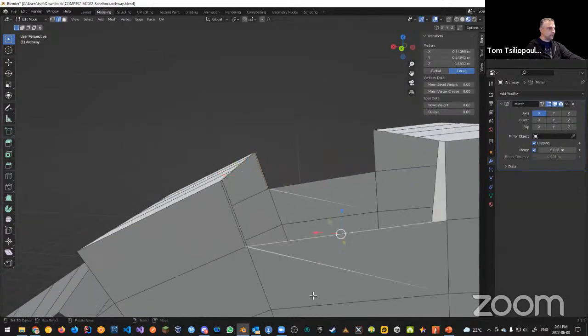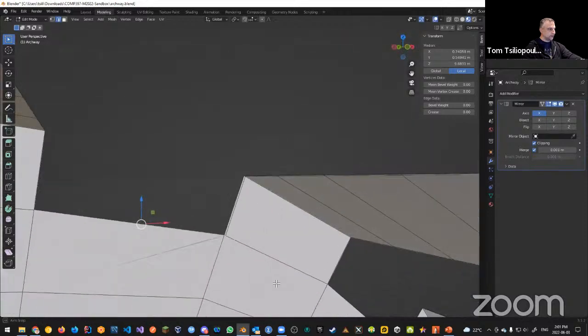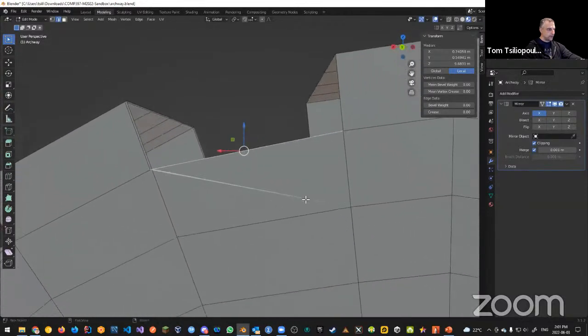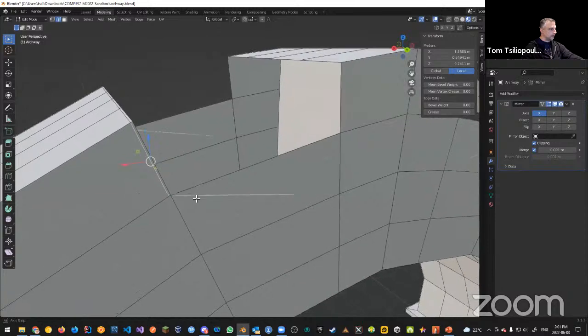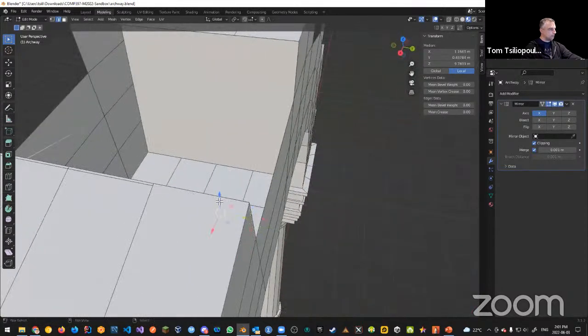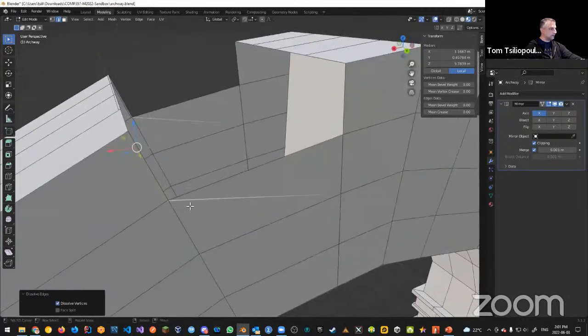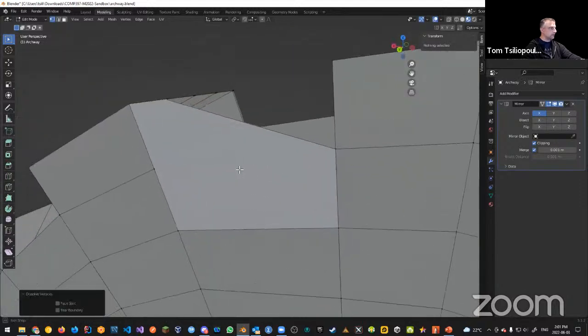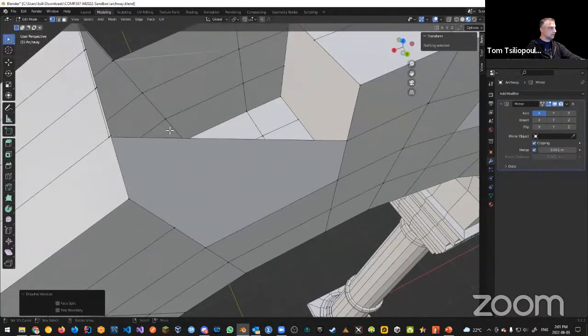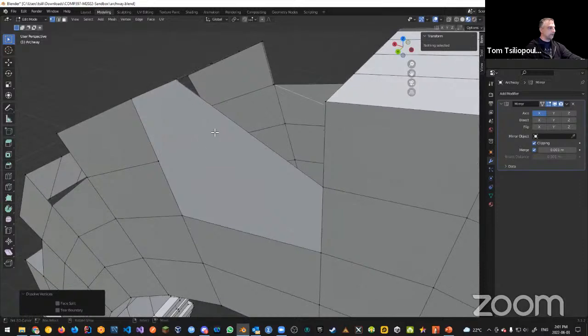And we've got more edges to dissolve, but notice that it also created an issue where I have this really weird thing here. Take a look at that, right? Where I have this edge here and here. And if I click dissolve edges, it says, yes, I can try, but unfortunately that's not good. So I can also convert this to vertices, and I can see if I can try and get rid of these verts. So dissolve vertices, but then you get something that looks weird, that looks like this. And this is just a matter of the way I did it. So again, I got to fix these problems before I go on. This is my issue, not yours.